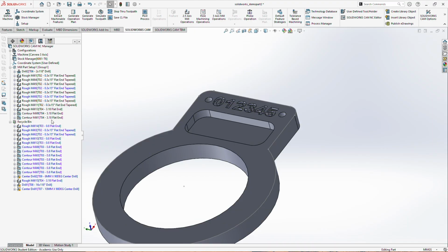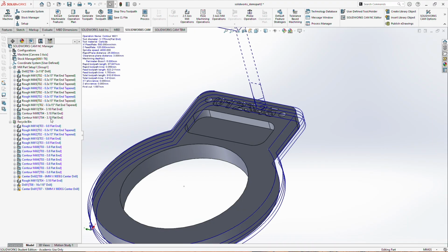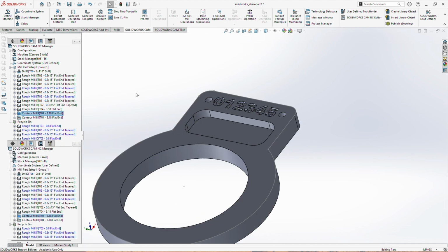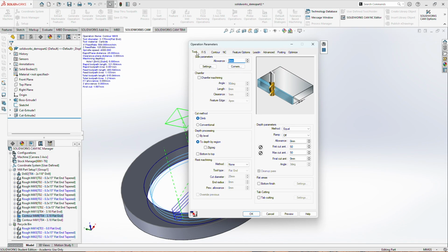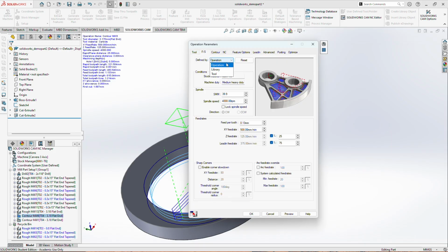And then it looks like we just have 2 more tool paths, which is our center hole and our outer hole as we go here. So let's go ahead and edit this center tool path. Let's look at what tool it decided to use. It's using the 3.175 by 12 millimeter bit, which again is what I would choose. Let's go to feeds and speeds and set this to be based on our tool defaults that we've set earlier on in our first video.